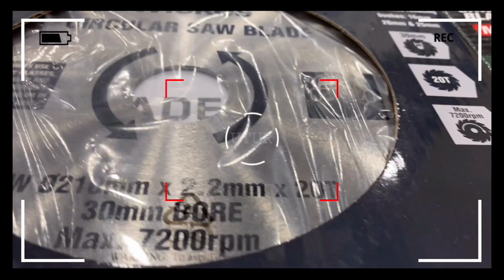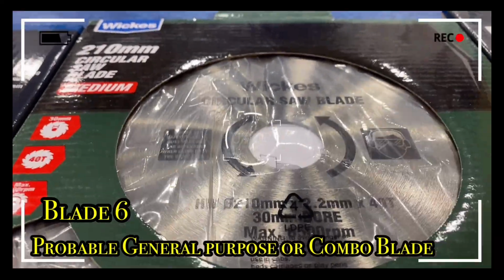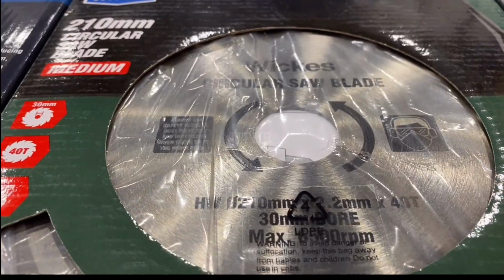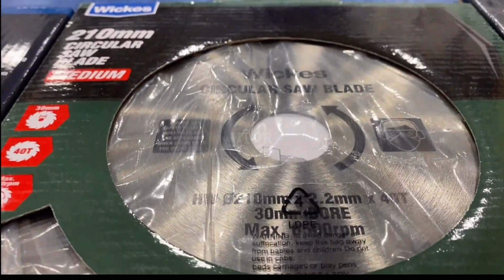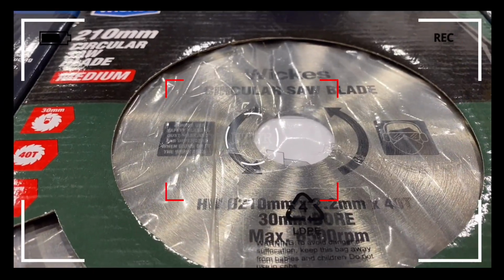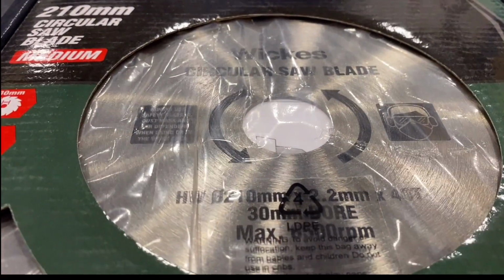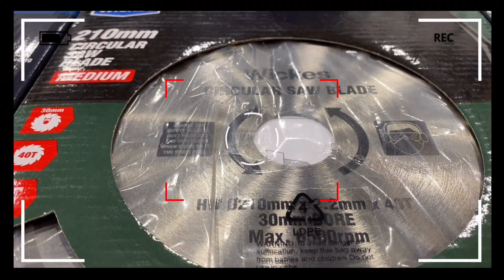The next blade has got a 210mm, 8.25 inch rim, a 2.2mm kerf, 6500 RPM and a bore of 30mm with smaller gullets. It can be used for medium ripping and cross cutting, so I'd be more inclined to say this is a general purpose blade or a combo or combination blade.